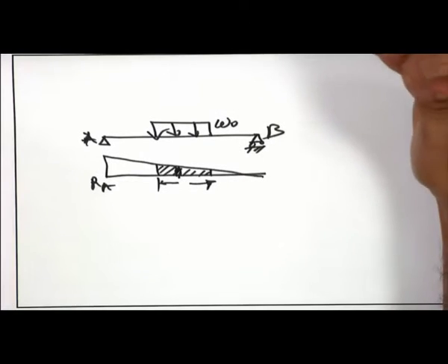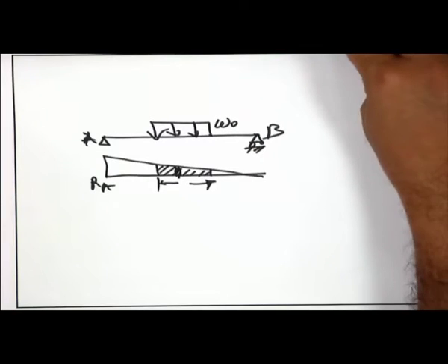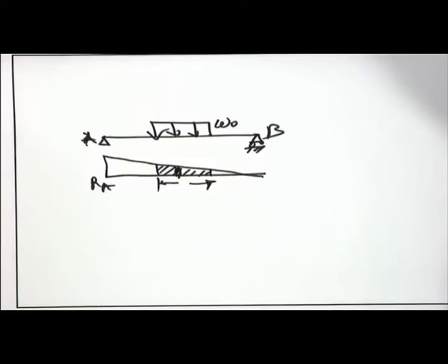So, the area under the curve accounts for the uniformly distributed load. There is no separate diagram for separate loading. Probably this was the confusion. You are drawing the influence line diagram for a unit load and finishing it, that is it. You have the influence line diagram ready for concentrated load, multiply by the ordinate. For the uniformly distributed load, find out the area multiplied by the intensity of the load.